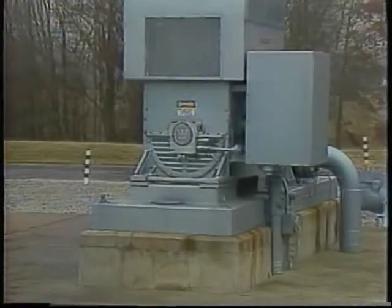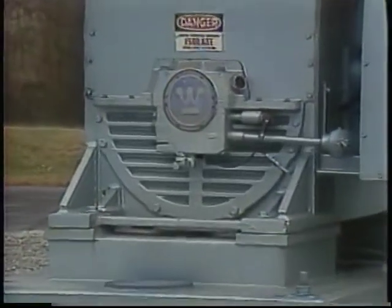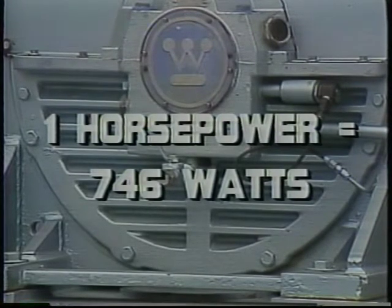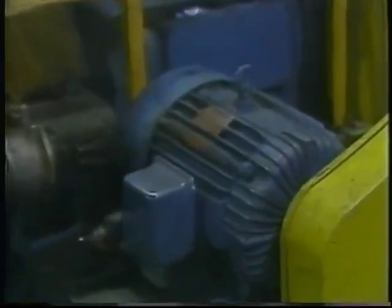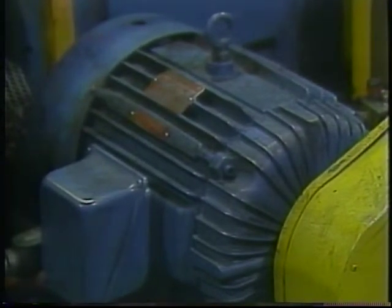Now, what becomes of the watts into a motor that are not converted into horsepower? They get converted into heat. 1 horsepower equals 746 watts. So a perfectly efficient motor would produce 1 horsepower for every 746 watts of power consumed. In practice, since motors are not perfectly efficient, it always takes more than 746 watts to produce 1 horsepower. The extra watts heat up the motor.